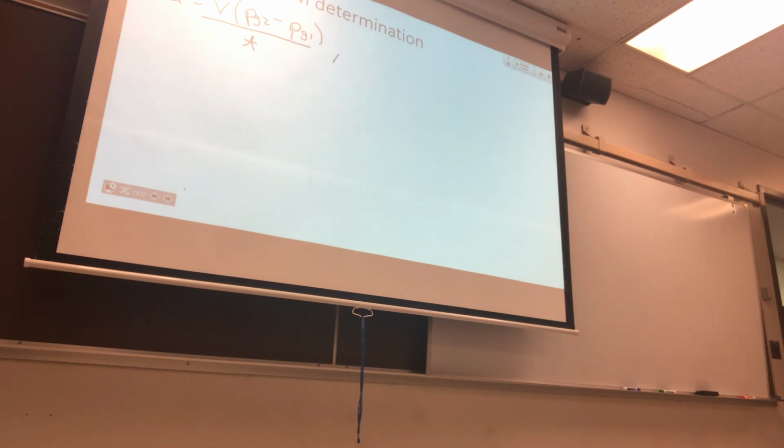Okay, on this equation, there's some other pieces here we want to add so we can convert and get what we want. So if we have, say, gallons and we need to get to our feet, we've got a 7.48 gallons per 1 foot cubed as a conversion factor. Our next conversion factor gets us to our standard pressure and volume. So that's that 14.7 in our clicker question.